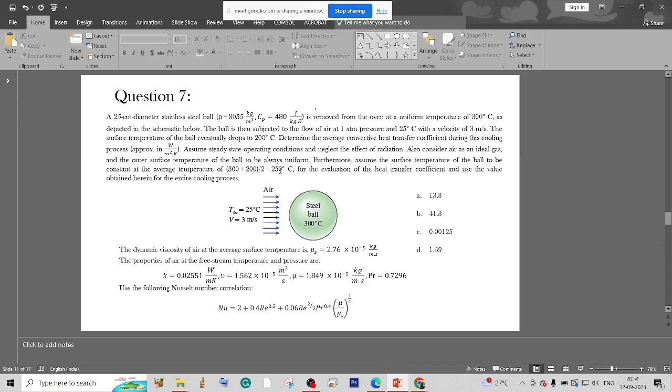So with this assumption, the time of cooling is determined. Here we will get some value in terms of joules, 3163200, and this will be in terms of joules per second. If we do a unit balance, we can clearly determine the time in seconds from both of them. So what we will do is Q total upon Q average. Q total is the total heat changed in the body by m c_p delta T, that is 3163200, upon the heat being transferred by the body to the atmosphere, which came to 609.3.